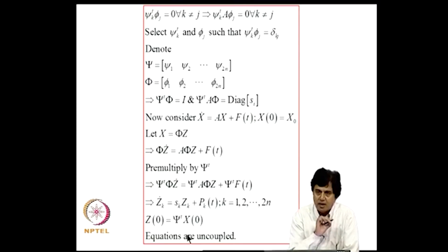So, the equations are uncoupled. The point is therefore that we can uncouple equations of motion in a very broad class of linear time invariant system problems, and that always helps us to represent solutions in a somewhat revealing way as a summation. So, we can understand the behavior of the resulting transfer functions by considering the contribution from each of these terms in the summation.